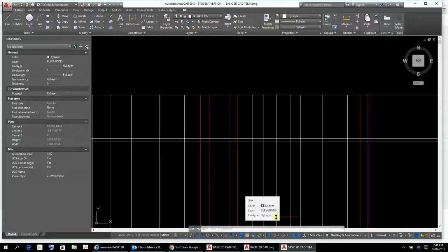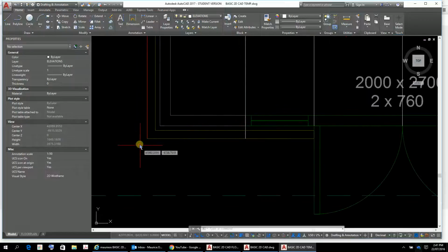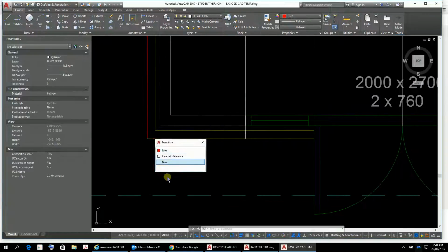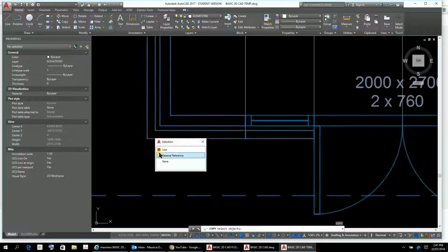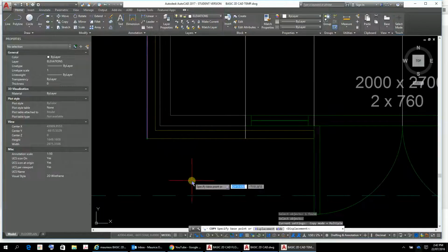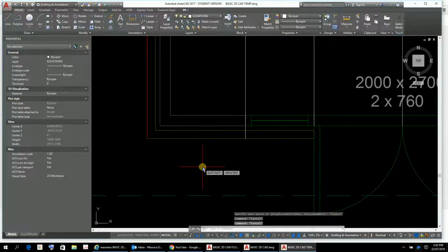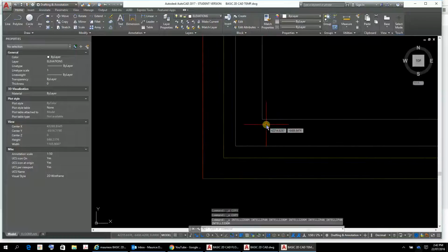Well, actually, that's the brick line. We actually want those there to be at the frame line because that's where the truss is. So we must be continually CP enter. Okay, CP enter that line. Finish. Things not going quite well. Control Z. Yes. Okay. Right.